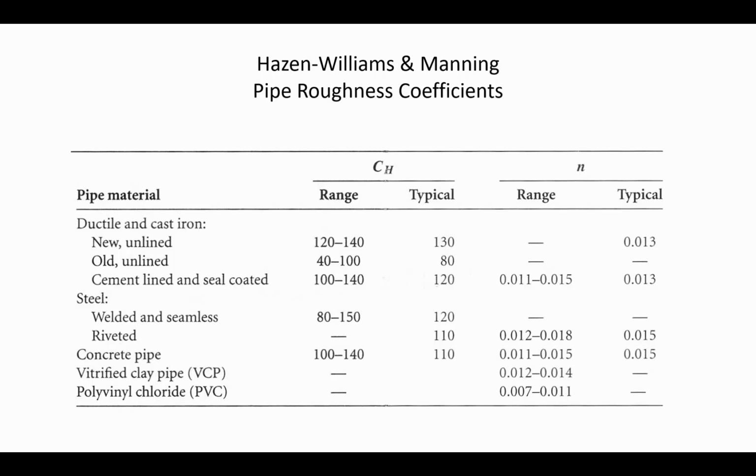But for galvanized steel culverts, the n value of 0.024 I think is pretty common. So it's kind of halfway between what you'd expect, because corrugations can be pretty large. You know, the diameter variation for a corrugated pipe may be on the order of inches. And so the effect isn't that dramatic in the n values that you'll find.